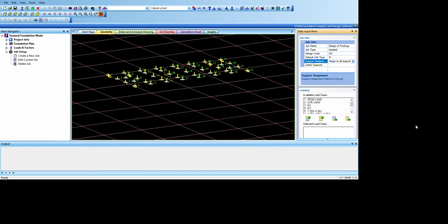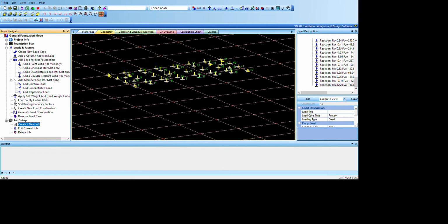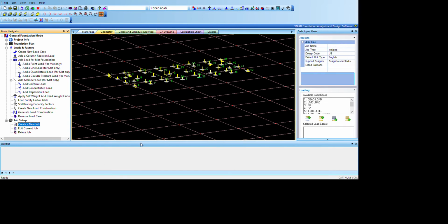Okay. Now, for the available load cases, you will see here that the load cases placed here are also the load cases we have done in our STAAD.Pro modeling. But in case you added loads and load factor combinations here, automatically this will add up to the list of available load cases you have in this selection box.